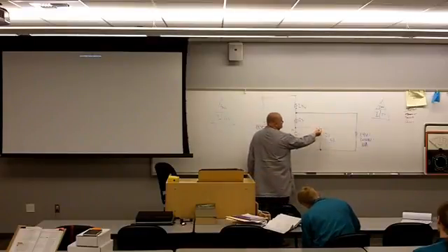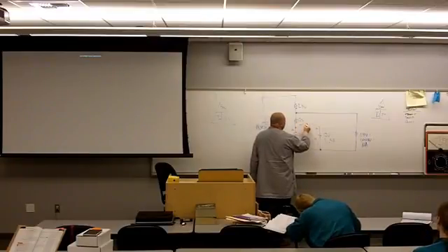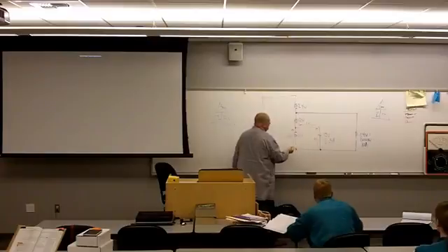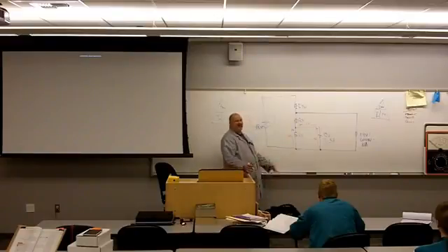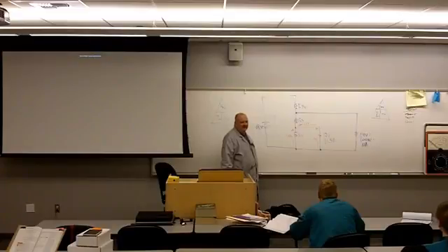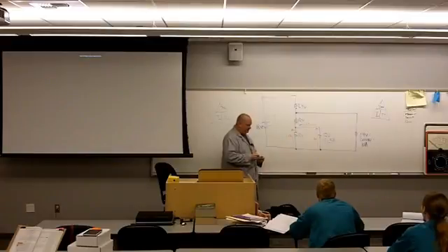All the current that comes up through the radio is going to come here into this node right here. So I've got 0.5 amps coming in from this angle. I've got 1.05 coming in from this angle. Can anyone tell me about how much current is going to be going through this? How'd you come up with that? It's a current divider. The node, they have to combine again.